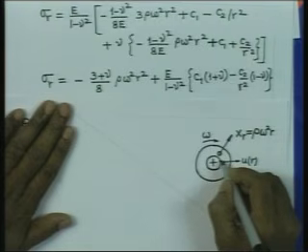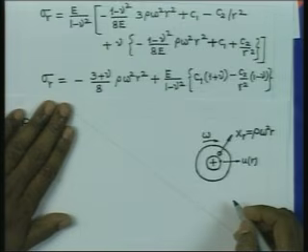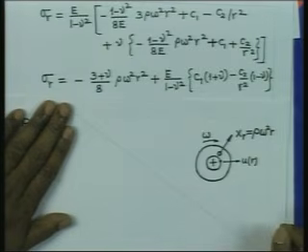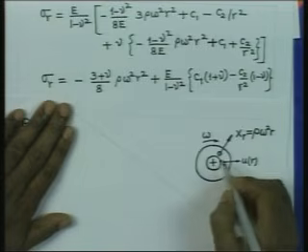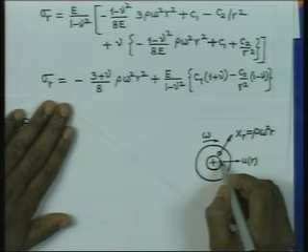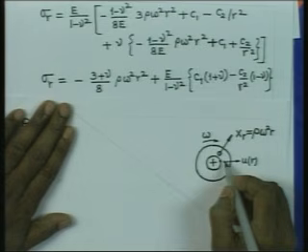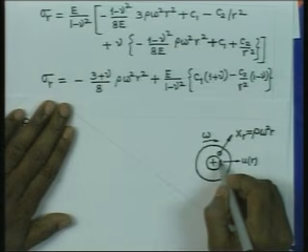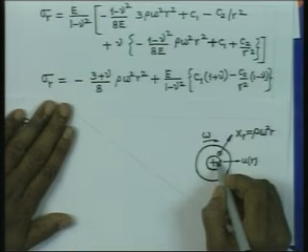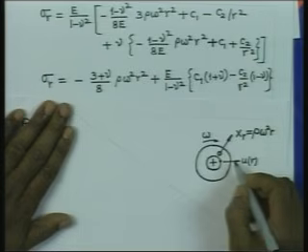The material which is just lying on the right of this inner surface is trying to move radially outward. So, therefore, it will be pressing the material lying to the right of it, but for the outer surface there is no material lying on the left of it. So, therefore, there is no radial force acting on this surface.